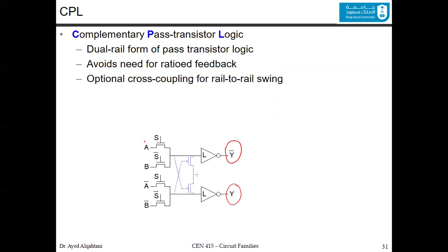The problem is when these values, A and B, are equal to 1. That's a problem. So what happens is you have a VDD here that's charging both nodes that might cause trouble when they have a 1. So this one will be connected to this value. How is this happening? If the one here is the one that might be degraded coming from here or here, if it's a 1, then here it must be 0.